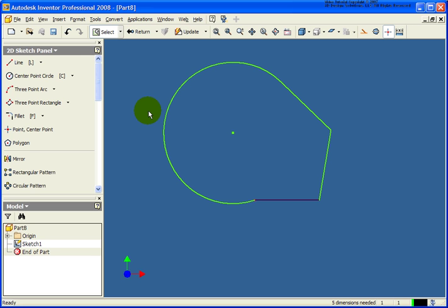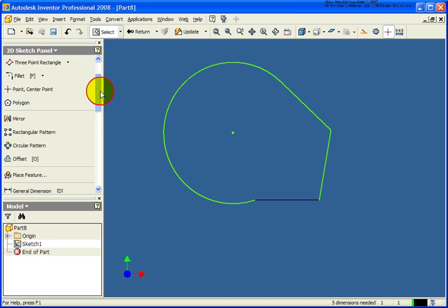One last point to make in regards to applying sketch constraints. After I'm applying these constraints, it's also removing the number of dimensions that are going to be required to fully constrain the sketch. In the geometry that I have up on the screen here, you'll notice that it shows that I have 5.